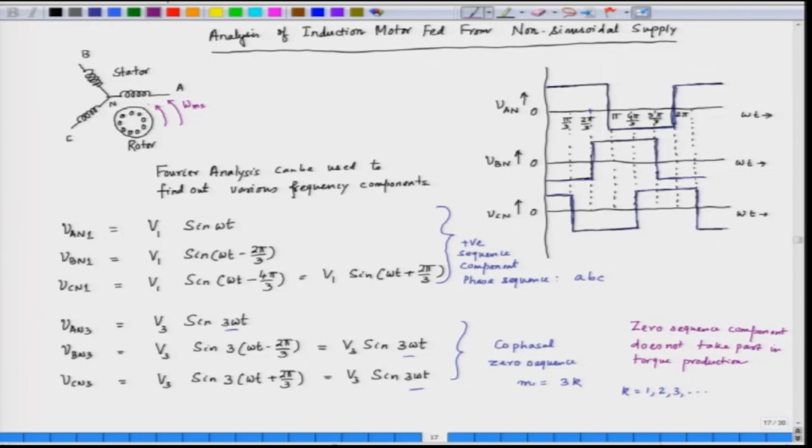This follows the stator field. So, we define a slip here. Slip is defined as (omega ms minus omega m) by omega ms. Now, this is the definition of the slip when we have only one frequency present, the positive sequence component. When we have a positive sequence component and a negative sequence component, we have different slips for different sequence components, even for different harmonics.